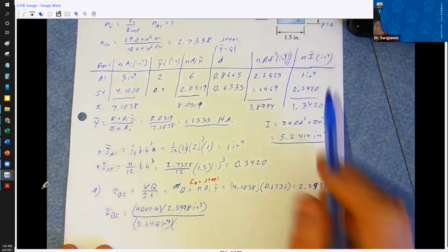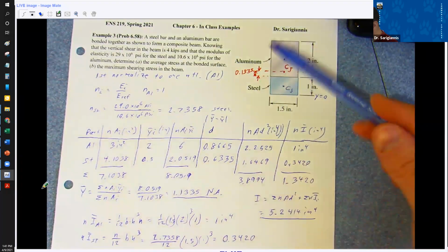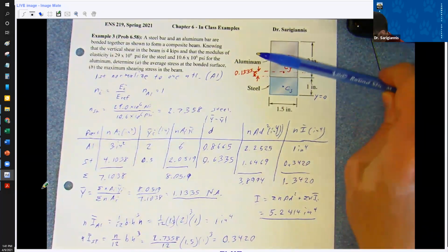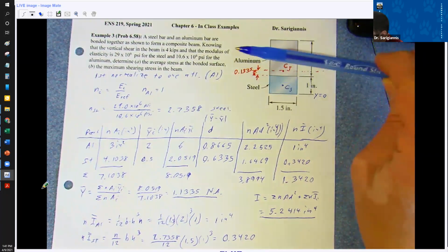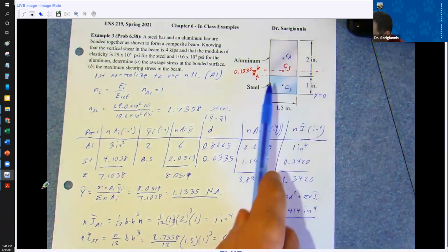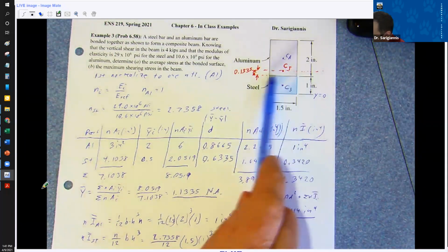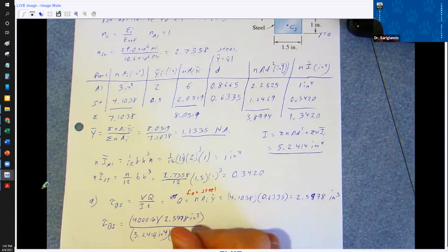And the thickness here is just the thickness, it's the width now, right? You're looking at you want to find the shear, right? The stress at the bonded surface. So that's the stress on that surface, right? And the area is basically, it's in and out of the page, but it's the width that you're using. Width of that surface. That's what the thickness is. 1.5 inches.